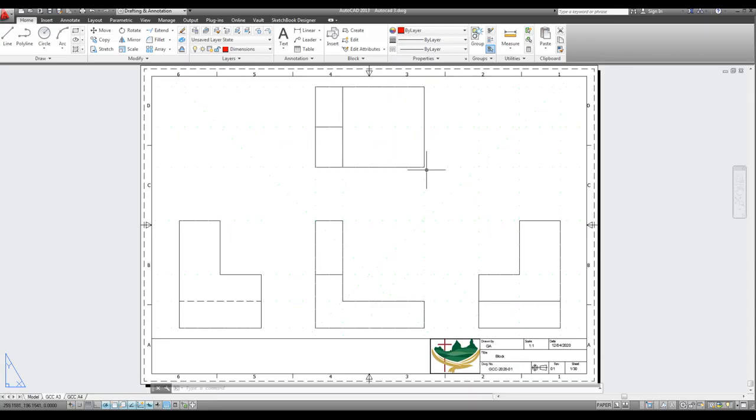But you're not supposed to physically dimension a 3-dimensional drawing. The dimensions only go on 2-dimensional drawings. And dimensions only go in paper space. You don't put dimensions on in model space either. That's the correct protocol. You may see it done differently, but this is the way that the software is designed to be used.